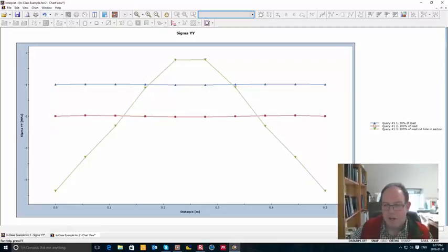So stage 1 is, we got 1 MPa of stress, and that represents 50% of that load, and you can see it's very uniform, so everything agrees. St. Venant's principle is correct, and the load value agrees with what we entered into it. The next stage, 100% of the load or stress, you can see is 2 MPa in tension.